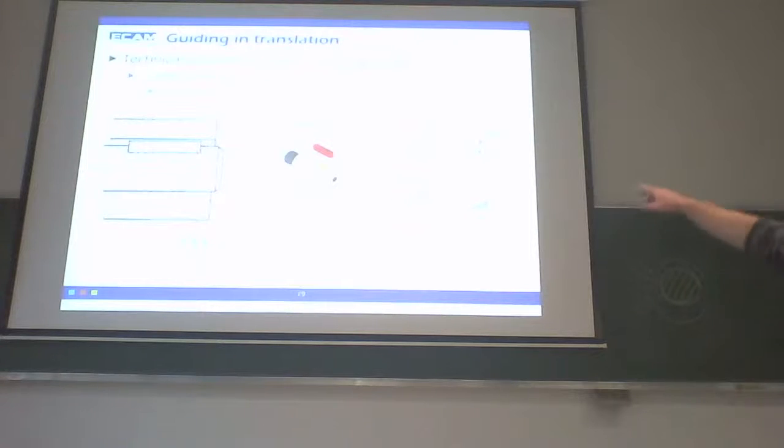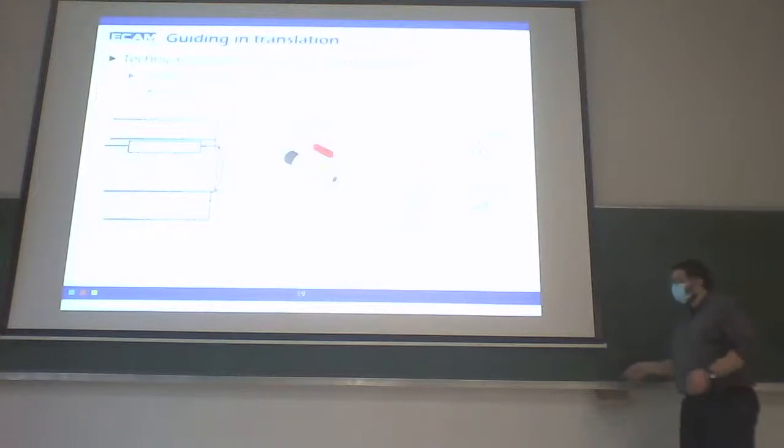You see with this diagram, I put the key inside the key seat. So like this, the key is fixed inside of the shaft. And after, the two flat surfaces of the key would be inside the groove, and these two grooves stop the translation. I can draw you the technical drawing in the opposite direction.